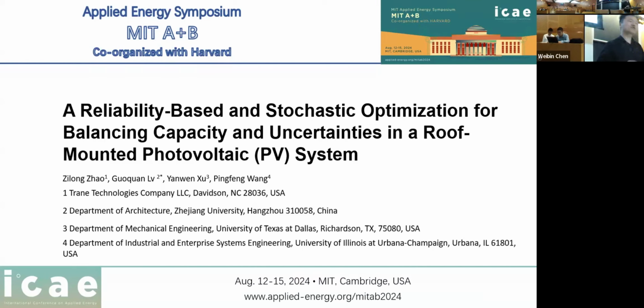Before jumping into this topic, I'd like to give you a bit of background introduction of the motivation. When I was working back in school, I was working on the geothermal heat pump system, basically using the ground source heat pump to replace the cooling tower, using the ground buried heat exchanger. When it comes to ground source heat pump systems, there are a lot of unpredictable factors, such as the layered ground thermal conductivities, the groundwater flow, and the length of the borehole. It really depends on the geology and other factors.